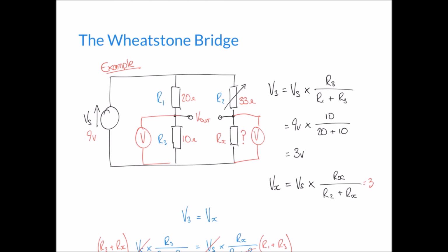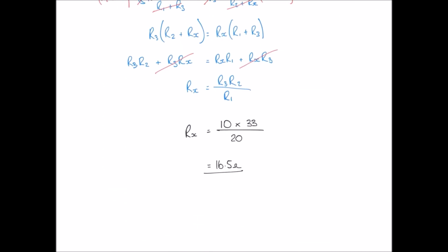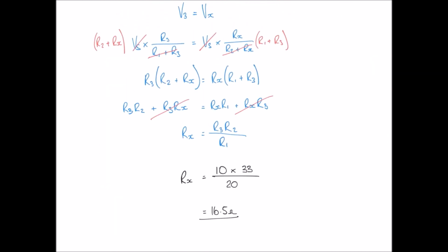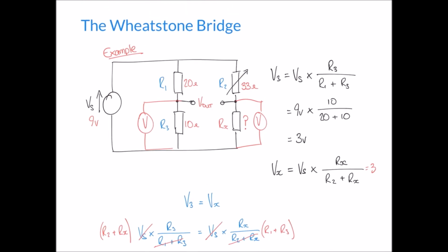Now, if that's the case, it doesn't actually affect our formula because, as you can see, R3 and R2 are multiplied together on the top of our fraction, the numerator. And if R2 and R3 are the other way around, we get the same result. We're multiplying them together anyway. But just watch out in case the position of the resistances has changed otherwise.